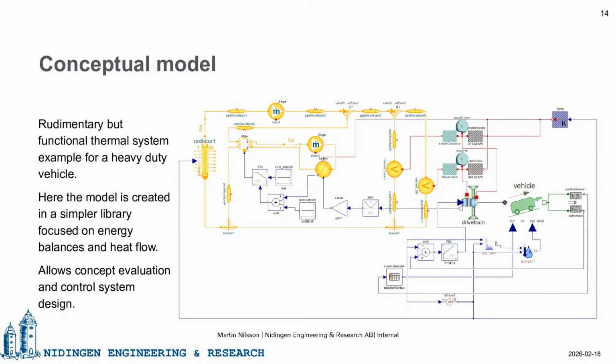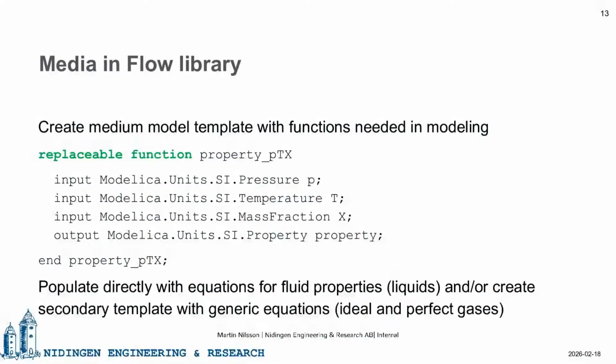So this is the library where I mentioned we have energy balances and heat flow only. You can see here, I put in my pump icon, I actually put in explicitly what my mass flow should be, and also in the subcircuit here. And then I explicitly define in this, I use a valve icon, but it's actually a flow splitter telling 0.7, the fraction 0.7 of this flow here goes in this branch, and then 30% goes here. I explicitly define that in this library.